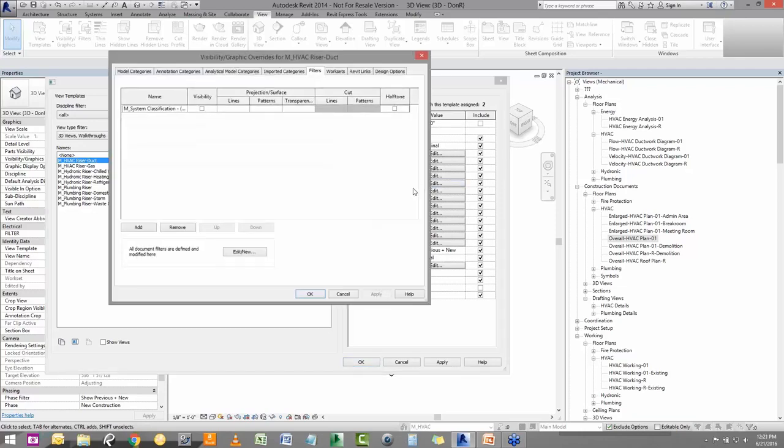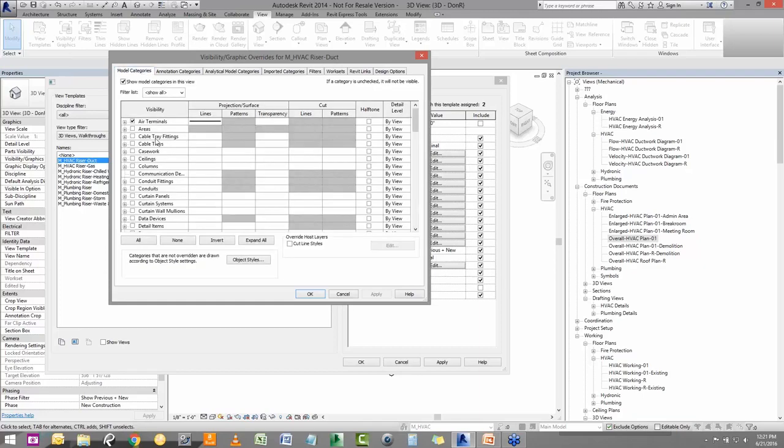So if I open up this view template here, you'll see that I have just a simple system class view template, and it's a not system class view template. If it's not there, the visibility for that is not checked, so this would not be visible. So therefore, this filter really isn't applied to this view. I'm not using it in this view to control things, because what I'm doing with this particular view template can be controlled mainly categorically here. So wherever categories don't quite cut it for us, which was a big theme in the piping soup to nuts webinar, filters really fill in the gaps.